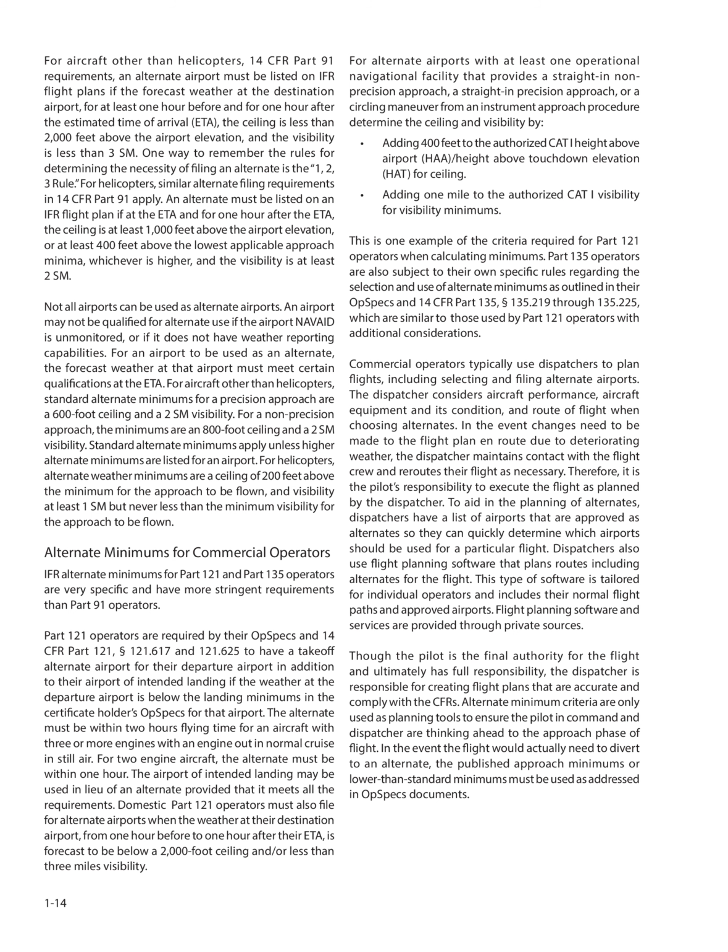Alternate minimums for commercial operators. IFR alternate minimums for Part 121 and Part 135 operators are very specific and have more stringent requirements than Part 91 operators. Part 121 operators are required by their OP specs and 14 CFR Part 121, Sections 121.617 and 121.625 to have a takeoff alternate airport for their departure airport in addition to their airport of intended landing if the weather at the departure airport is below the landing minimums in the certificate holder's OP specs for that airport.